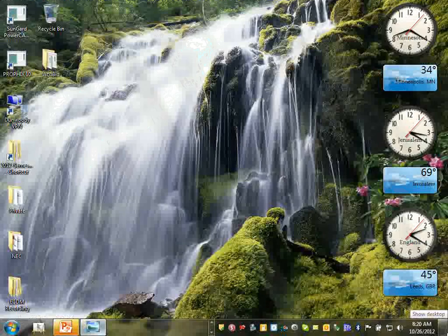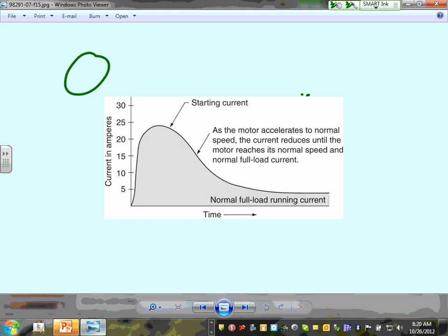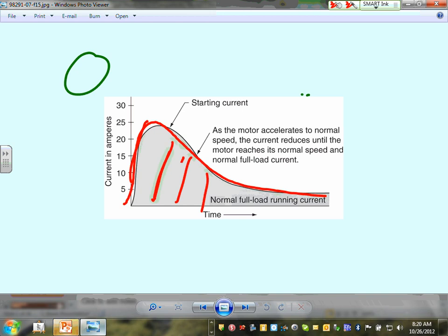Okay, this is a curve of a start current. When you start an equipment, the current is going to be so high, and then it is going to go all the way down. This energy, do you guys remember what Jerry was talking about the other day, this energy that they're trying to reduce? This is very similar. You start your motor, because of the inrush is so high, the current will go high. After 10 seconds, it tapers down.